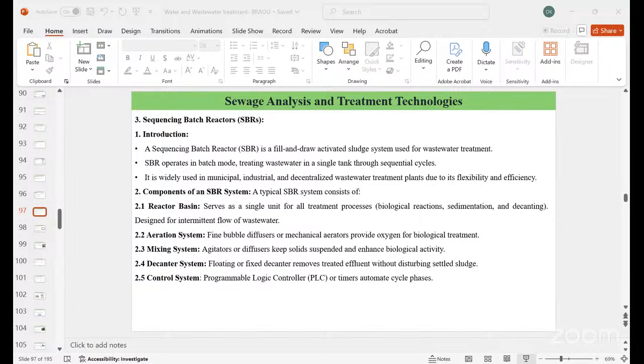The fine solid waste can clog biological filters and aeration systems, ultimately reducing their performance. And increased sludge production, where undigested solid waste increases the volume of the secondary sludge. Coming to the tertiary treatment, where advanced filtration and disinfection take place, filter clogging majorly occurs, and fine particles and microparticles can clog the advanced filters.